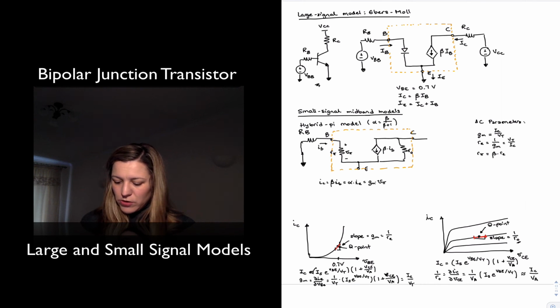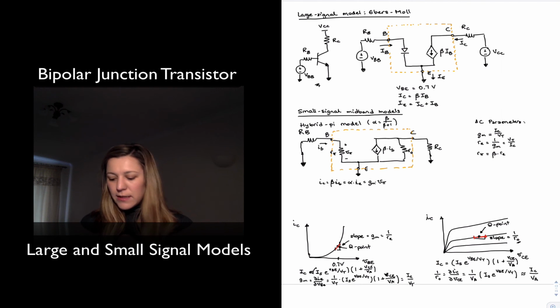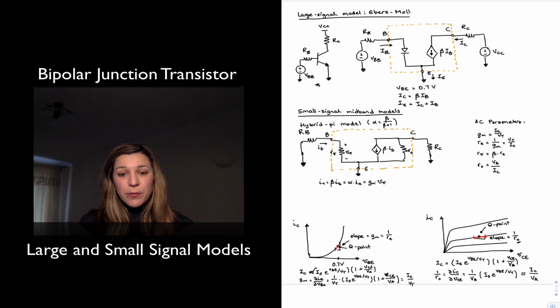And likewise, on the other side, we have a collector resistor tied to a DC source, VCC, and the DC source becomes a short in the AC equivalent circuit. Then my emitter will be directly tied to ground. So this will be my equivalent circuit. There is one more thing. I haven't written the expression for little RO, but I will do so. If 1 over little RO is IC divided by VA, then little RO will be VA divided by IC. So that's my hybrid pi model.